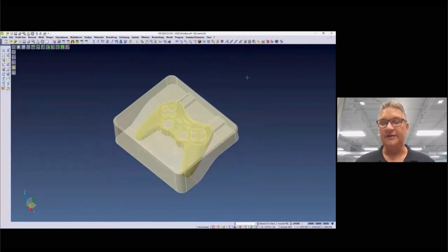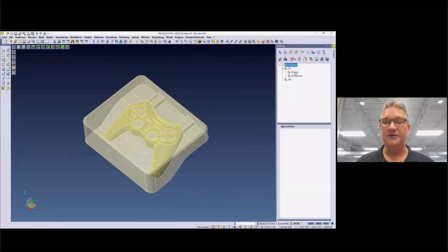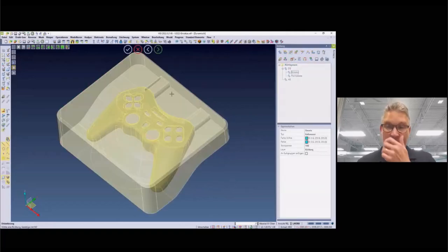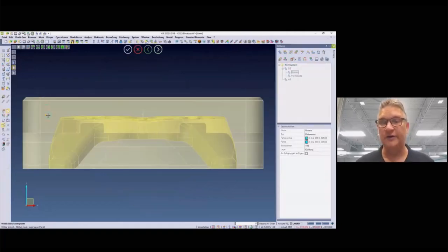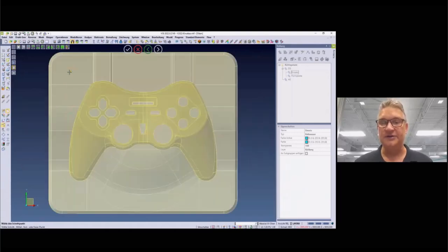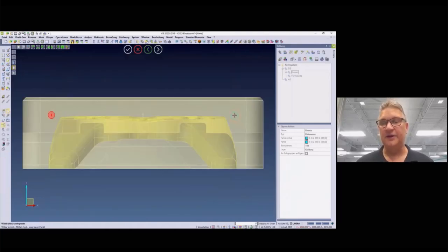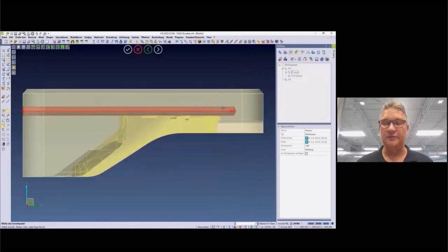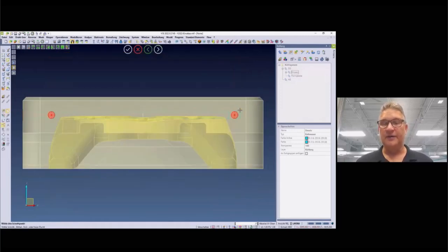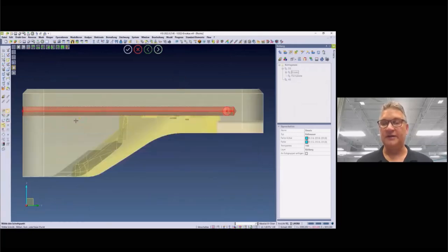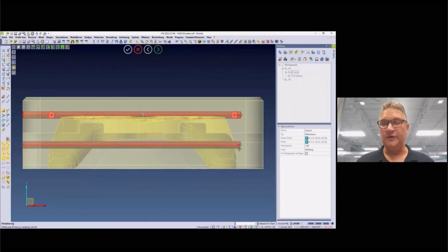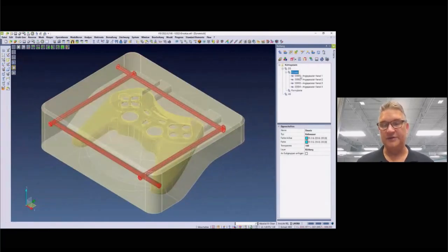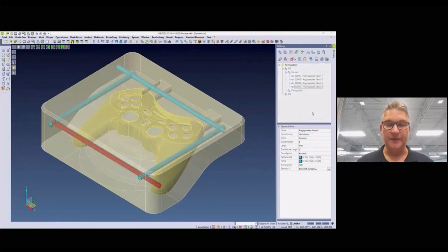After selecting a detail, you will need to decide the direction in which to add a hole. Once confirmed, the model will orientate itself accordingly to allow easy insertion of channels. After the application point is selected, the application switches to another direction to complete the first channel. Then we complete the first circuit by selecting the positive X direction for the through hole between the two holes just created. It is possible to ignore the collision messages, but you should check it out afterwards.